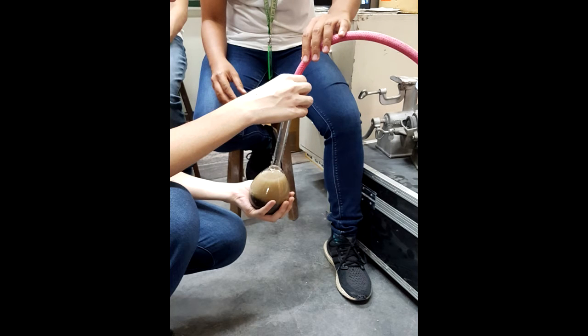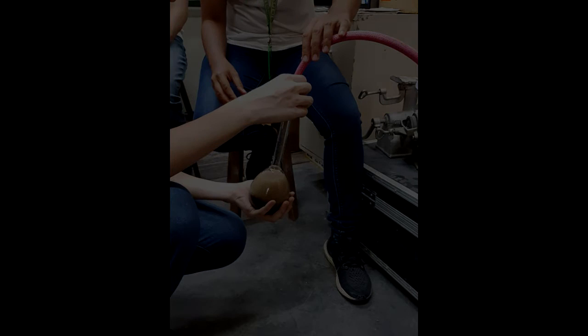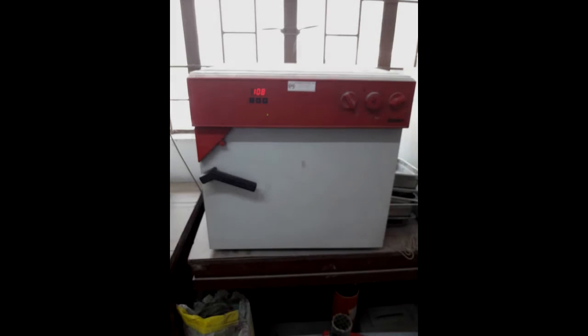For the established values according to the American Concrete Institute, the specific gravity of aggregate suitable for concrete mix is between 2.3 and 2.9, while the absorption is between 0 and 8%. For our experiment, the values calculated are 2.457 and 3.44% for specific gravity and absorption respectively.